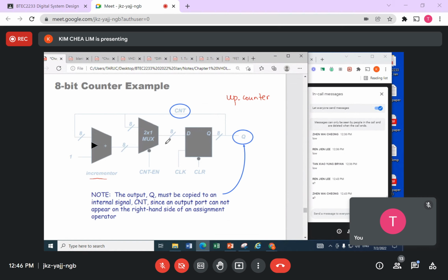Next, because there is a selection of count enable, it functions like a multiplexer. It decides: should I count increase, or should I not count the increments, things like that. So count enable will manipulate all this. It's active low. Actually, there are also 8 of 2-to-1 multiplexers inside here, 8 of them.